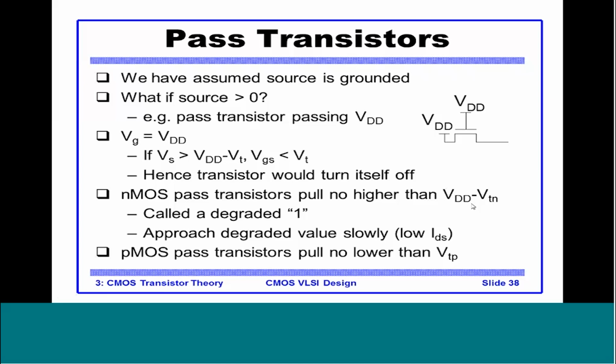That is why in earlier circuits we saw that NMOS is used for the pull down logic, not for pull up. In most designs, NMOS is only used for a pull down network, since it passes a strong 0. Correspondingly, PMOS will pass a strong 1, but it will pass a voltage which is no lower than its threshold voltage, that is VTP. That is why PMOS is used in the pull up network, because it passes a strong 1 but a weak 0.